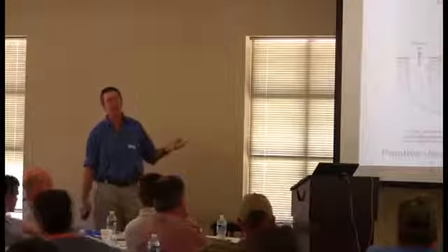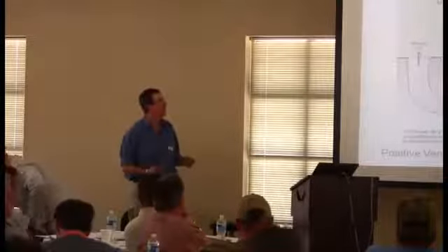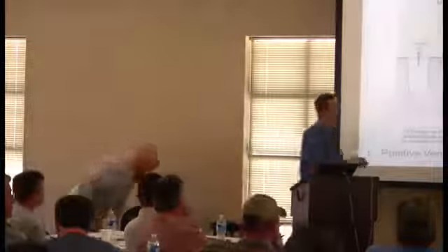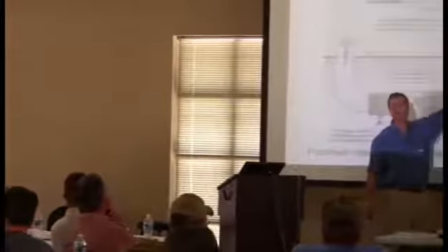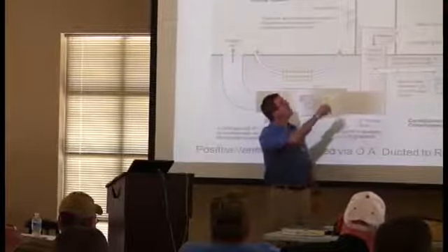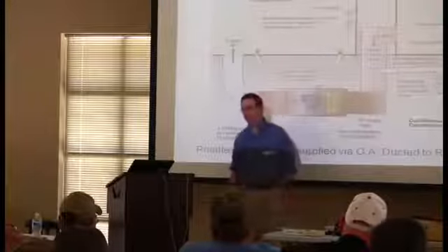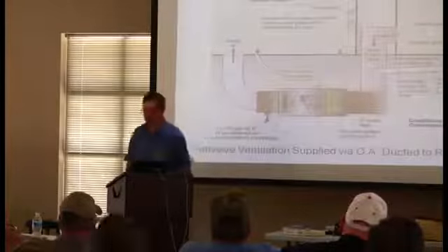So another approach that we use on a lot of EarthCraft houses is we simply duct in an outside air duct and we attach it to the return, so that when this system operates, most of the air comes from the house, but a little bit of air comes from the outside, and the house experiences a slight positive pressure.